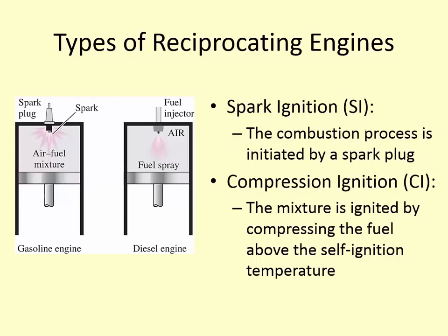Okay, so the two types of engine, we've talked about spark ignition, where the combustion process is initiated by an actual physical spark. So this air-fuel mixture is compressed, the spark plug sparks, and ignites it. Compression ignition has, instead of a spark plug, a fuel injector. So this cylinder is being compressed while it's fairly empty. Then the fuel is sprayed into the cylinder, and when it's at a high pressure, the mixture will ignite, which then causes the mixture to increase in temperature rapidly. So that's how the ignition process occurs in a diesel engine, that you have fuel injectors.